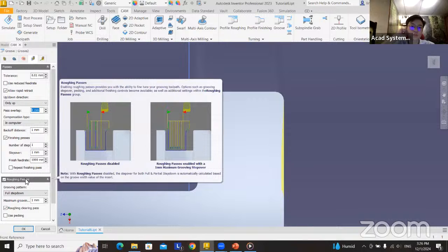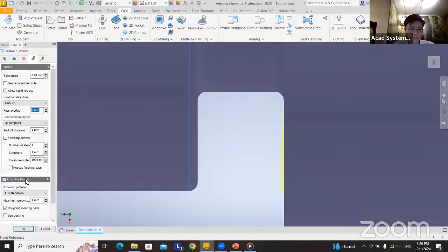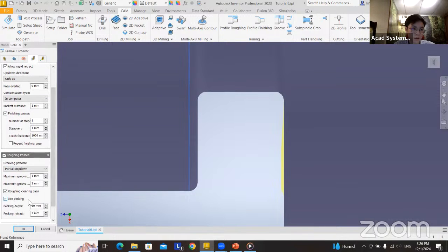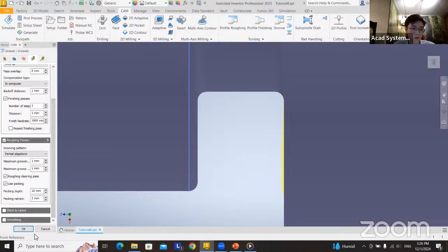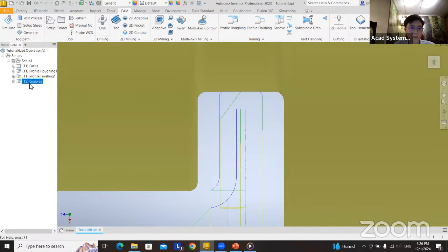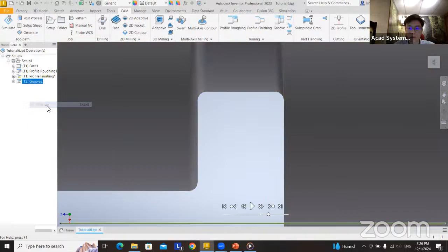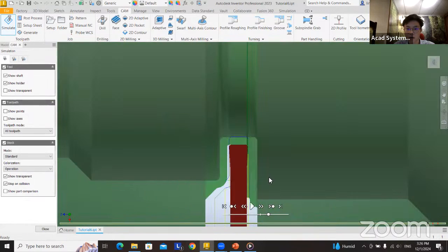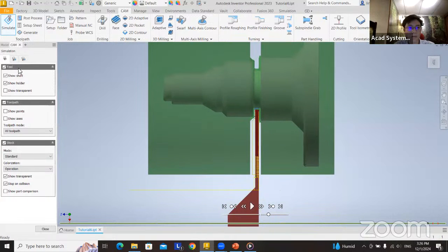These have to be troubleshot one by one until you get it. So I can possibly select partial step down, let it step down one by one. Use packing motion as well, so it will track. And let's try. So if it's still colliding, yes, it's still colliding. Maybe I'll leave it until next time. Maybe you can leave it in a YouTube comment once I'm done with this.